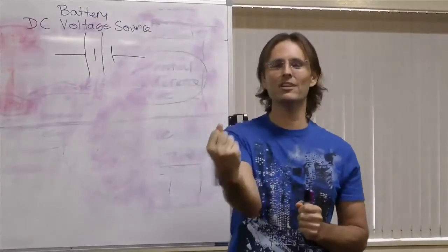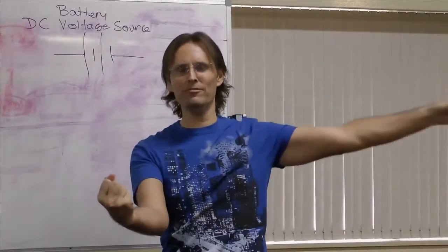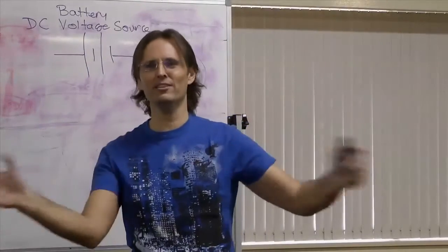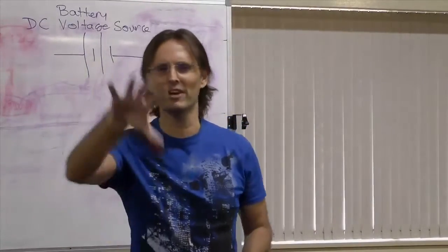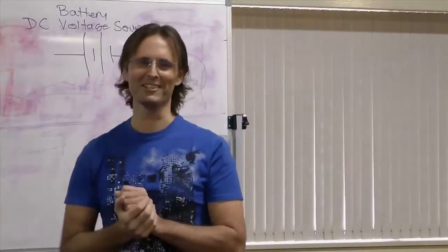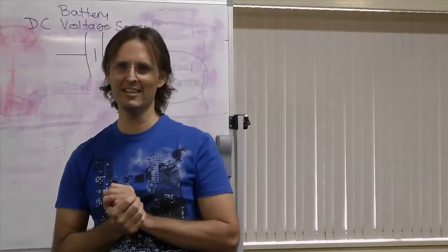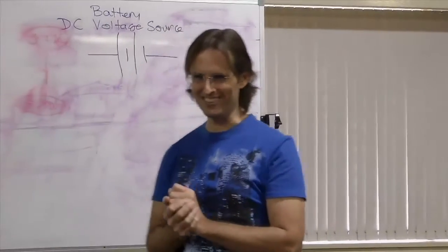If you've got to touch the wire anyway, and you've turned off the power to your house and you've made sure everything's off and you reckon you've done everything possible, still don't go and grab it with your hand. Touch it first with the back of your hand, and if you get no response from that, then you can figure it out and do something with it. Does that make sense? But make sure you do all the safety things first.